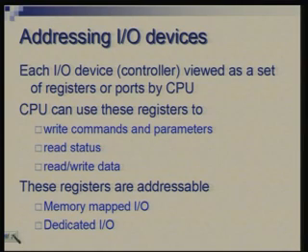So what do you do with these ports? You can, for example, give commands to a peripheral device. There would be some register in which a command could be given. So you load some code in a particular register, it will be treated as a command, and the device would be expected to work on that command. The command may also involve some parameters. For example, for a command to seek the disk, you may have to specify the track number and sector number.